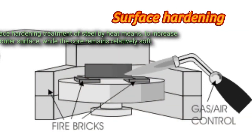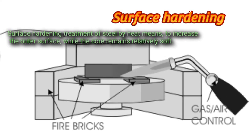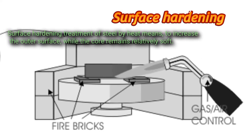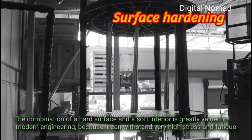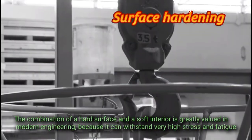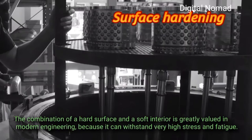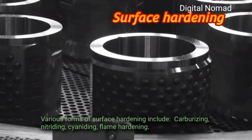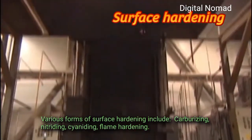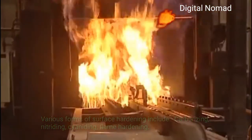Surface hardening. Surface hardening treatment of steel by heat means to harden the outer surface while the core remains relatively soft. The combination of a hard surface and a soft interior is greatly valued in modern engineering because it can withstand very high stress and fatigue. Various forms of surface hardening include carburizing, nitriding, cyaniding, flame hardening.